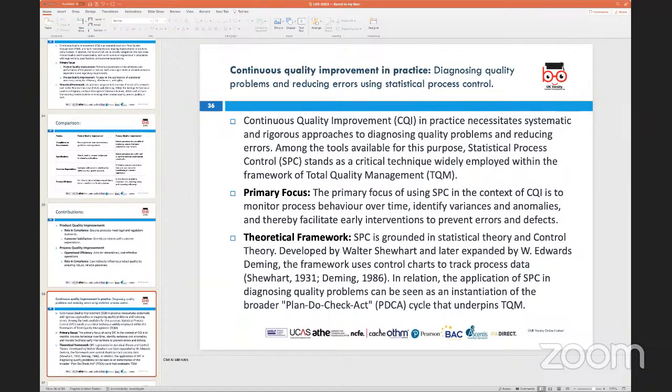And these variations essentially lead to what are called defects or faults. And when this is done using the technique of crunching data and data-driven decision-making to design control charts, which are used as benchmarks, it would be fair to say that they are utilizing what is called SPC or statistical process control to drive quality improvement within the organization or within the manufacturing of that particular product.